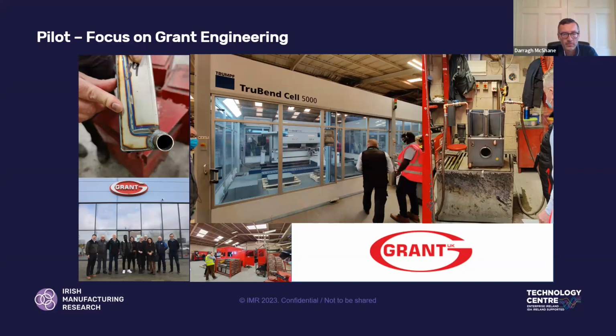So for the Quantic project in particular here, we deployed the application to the mild steel and stainless steel areas. This is where the steel panels are firstly laser cut, they're bent, and then welded into the final products. The operators then perform what they call a leak inspection test. You can see that on the right-hand side of the image there, where the newly assembled boiler is plumbed up to a pressurized water source, and it's rigorously inspected to detect any leaks or weeps in the assembly.